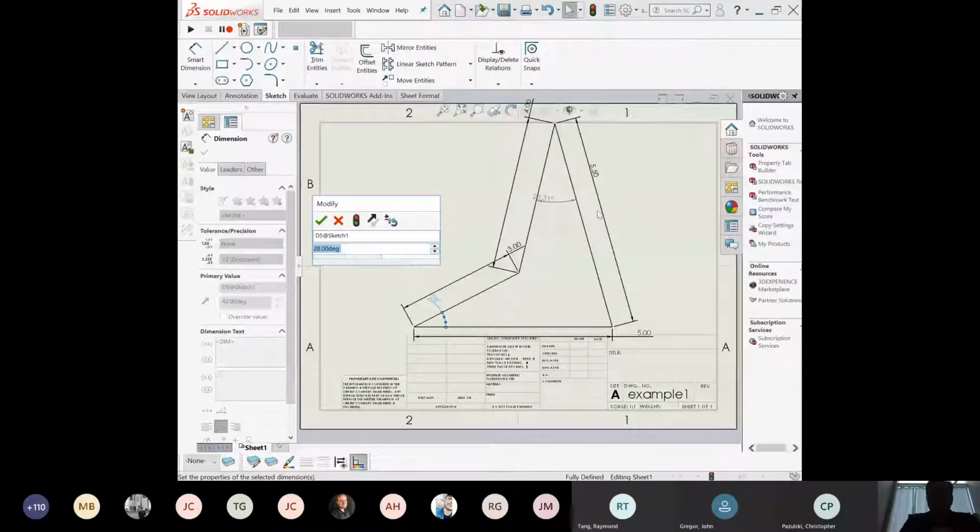And so if I want to hone in on exact angles for my transmission angle, as you'll need to do for your homework, you'll want to find the maximum value that the transmission angle can be. What you may find you have to do is drive this from the transmission angle rather than from the input angle.